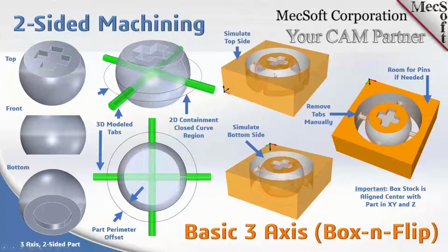you see we simulated the top side, and you'll notice that in the areas where the rods were, the machining skipped that area. Any geometry that's visible when you generate an operation in three-axis will automatically be checked against for a gouge-free toolpath, meaning it will not cut into that area.